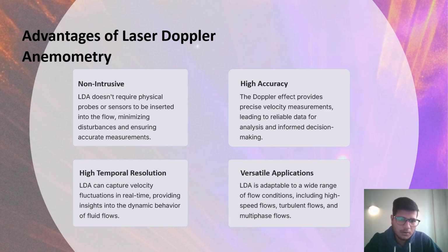And it has high temporal resolution, which means it can capture velocity fluctuations in real time, providing insight into the dynamic behavior of the fluid flow. And it also has versatile applications, which means it is adaptable to a wide range of flow conditions, including very high speed flows, turbulent flows, or multi-phase flows.